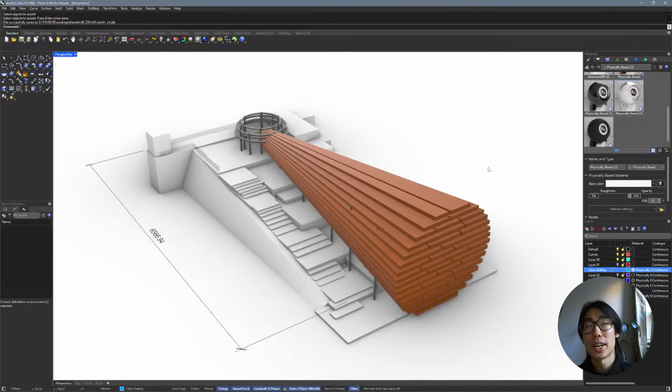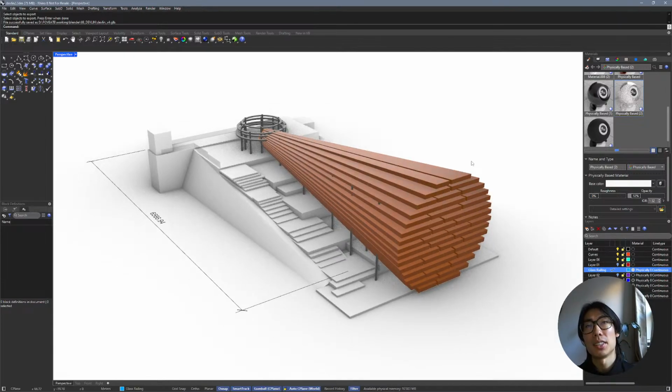Now, the great thing about Rhino 8 is this GLTF exporter is now natively built in using C++, so it's super fast. The other versions of Rhino before Rhino 8, unfortunately, do not have this, so they're a little weaker in that sense. You can use the package manager to install a GLTF plugin, and that works as well, or you can export out an FBX or 3DM from Rhino to Foveate. The downside being those are much, much bigger file sizes because they don't support compression and cannot be optimized as well, but they are doable. So now we've exported this.